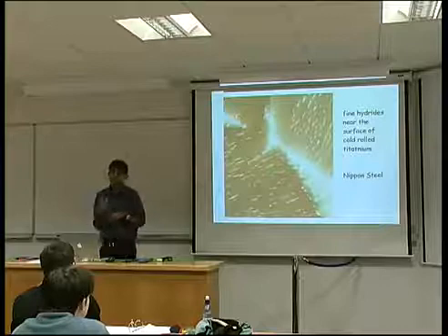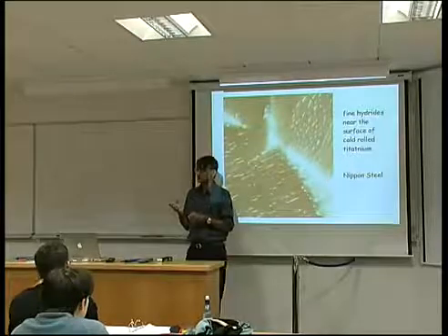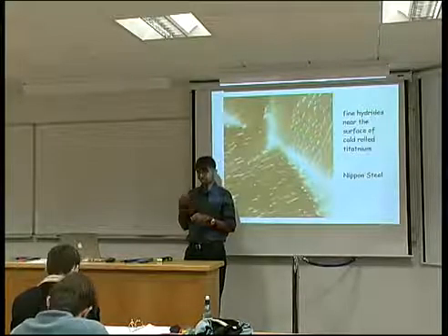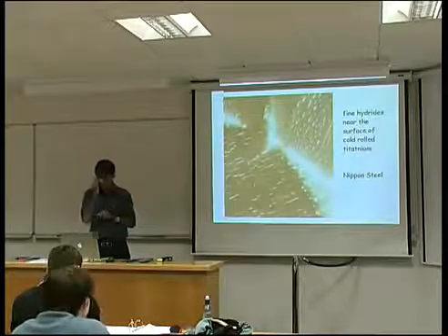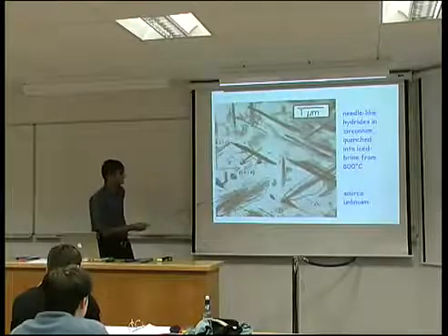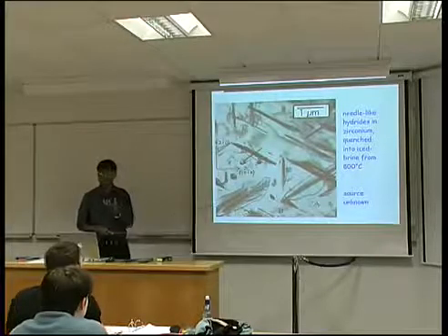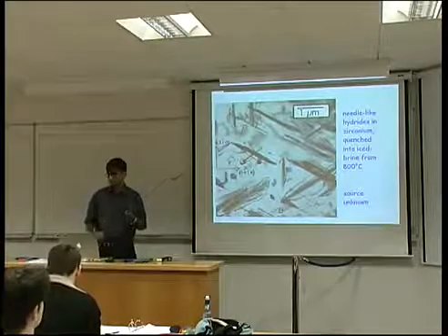Now, of course, if you're using it for fuel storage, then that's not very important. But if it is in a structural application and you get hydride formation, that is very important because it will be severely embrittled. And it's not just titanium which does this. Zirconium, for example, also forms these hydrides with a very large volume expansion. So it's an important problem.